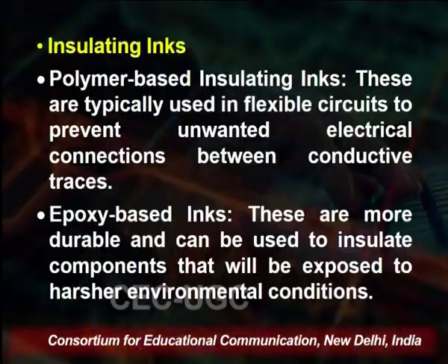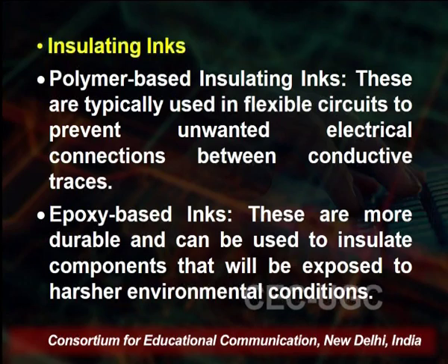Means whenever we do not require any conductive region, we use insulating ink that will produce the barrier in between the conductive devices. Polymer based insulating ink we can use here, epoxy based ink we can use for the insulating, or we can use the hybrid ink also.